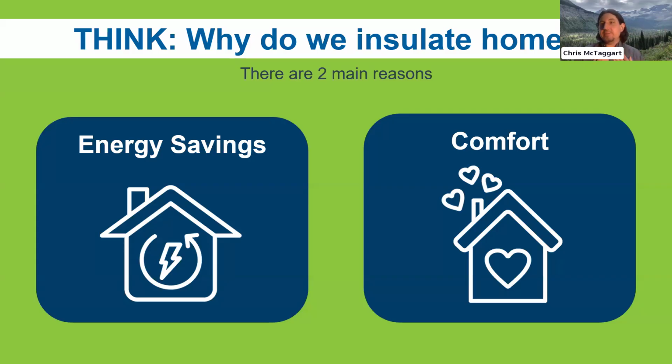Human beings, we're about 98 degrees, and generally speaking, we want to keep our houses at like 70 degrees. Well, that means we have this thing called radiant heat loss off our bodies. We're the warm thing and we're losing that heat to the surfaces that surround us through a process called radiation. I won't get too nerdy about that, but it's a big deal. That's why people feel uncomfortable when they're close to, say, a single pane window.